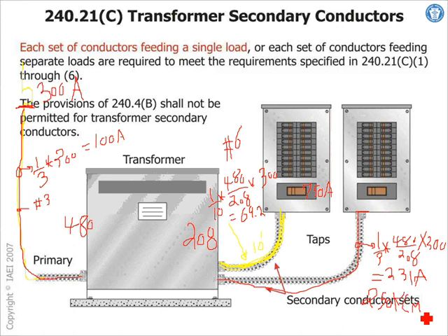How about inside the building? How about if you're outside the building? Have you ever thought, guys, on farms and all the stuff, tapping a conductor right on the top of the pole? How do you do taps there? Do you put overcurrent protection devices all over? Inside the building, these are the rules. Outside the building, the only rule is you can tap and go as far as you want.